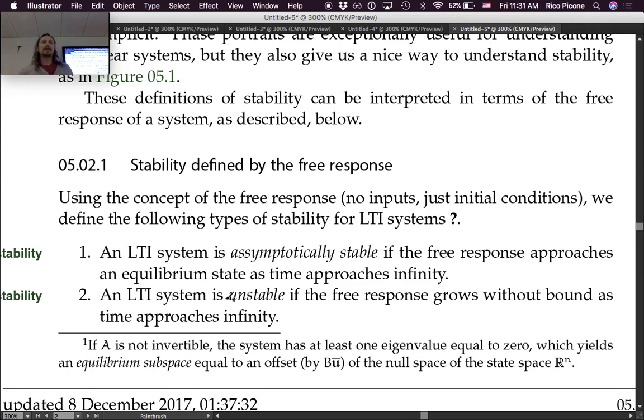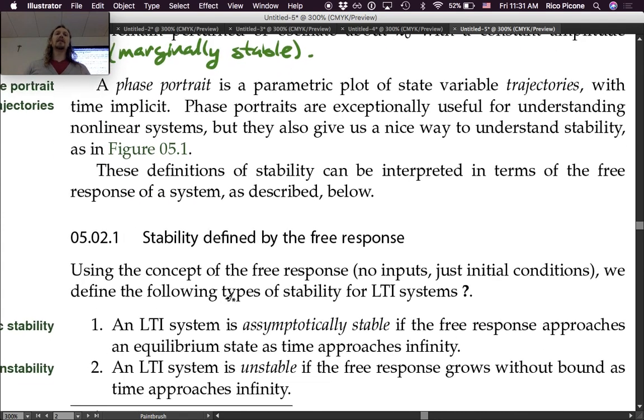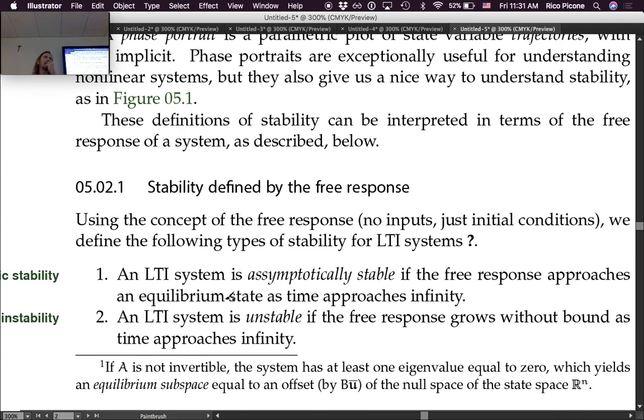Cool. So, excellent. So this is generally state space thinking for stability. Okay. The same stuff applies if you have input-output differential equations. Say your output can't be changing. So instead of just having a bunch of states that have to have time derivatives equal to 0, your dependent variable y has to have its time derivatives equal to 0, right? So you can think of it in those terms as well.